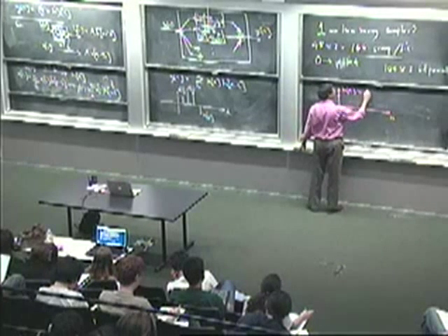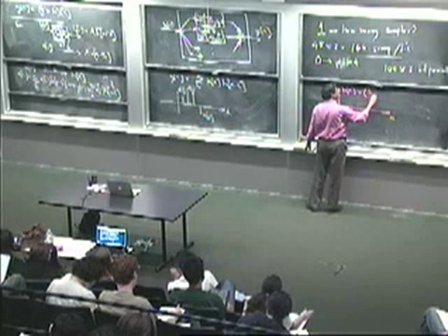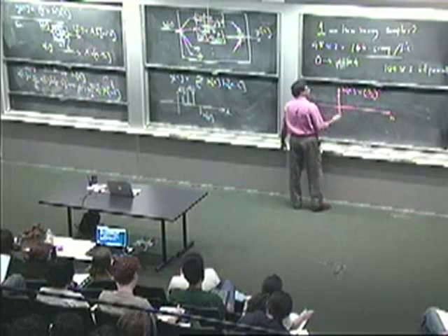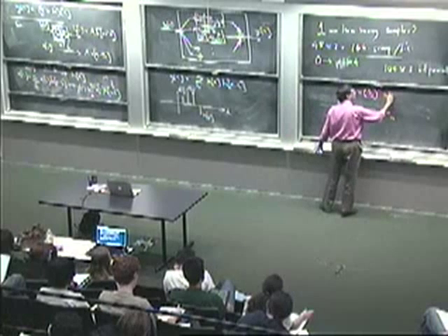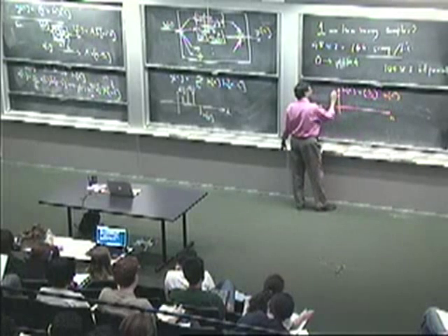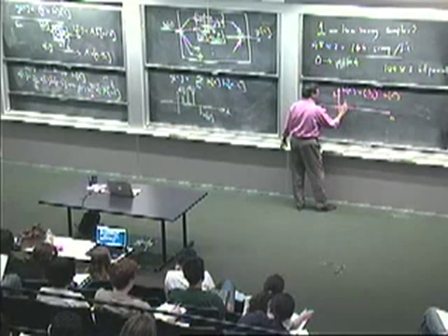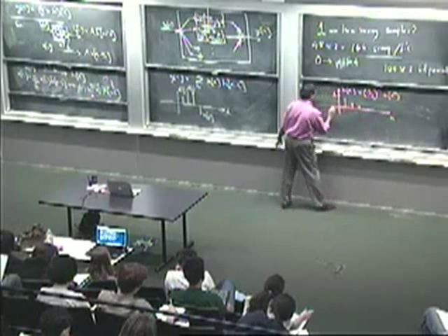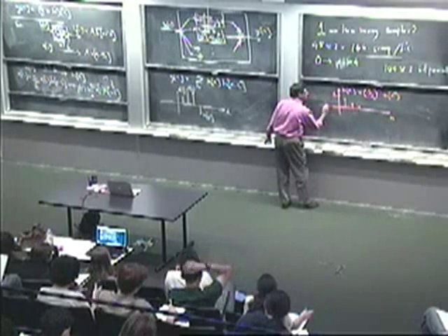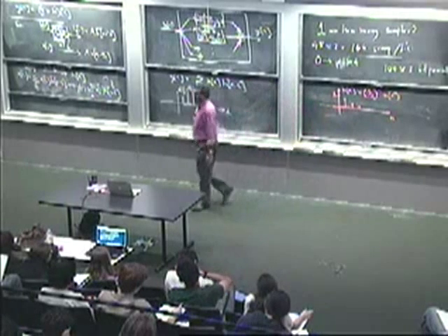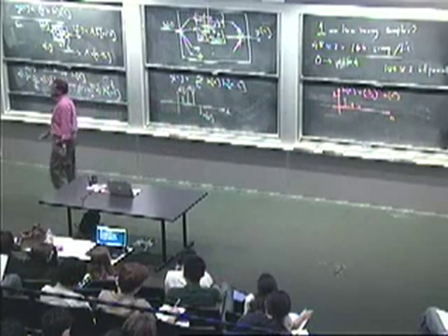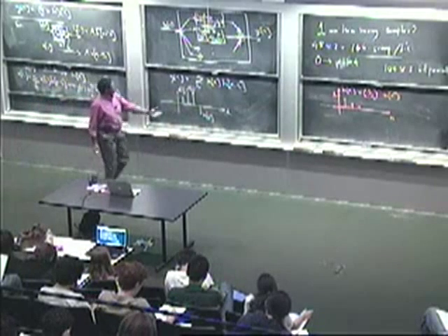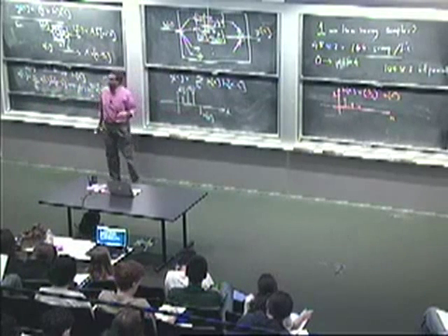Let's say that this is 1/2 to the n times u of n. So for positive time, it's kind of a decaying geometric series. And for negative time, it's 0. So that's an example of a unit sample response of a system. So if that's h of n, what does h of minus k look like?